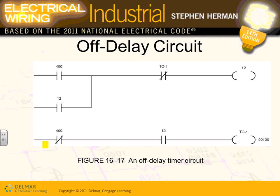Okay, so we have the off delay and on delay. I'm sure you guys know, with off delay you delay the off, or you delay the on. When you put in your timers, you're going to see, you turn off the system, and after the system is turned off, 10 seconds later, do action. So these are the programs that you can do. We'll see them in a second too.